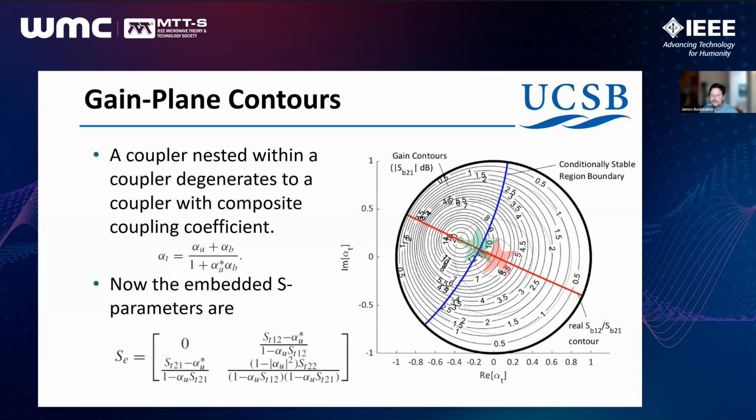And so we can keep adding feedback, and we start to walk into a place where we have positive feedback that's conditionally stable, and ultimately we may hit a very high gain, but that might not be realizable from the standpoint of stability in an actual circuit. So this gives us an idea of the type of alpha we'd like to achieve with that particular HEMT.